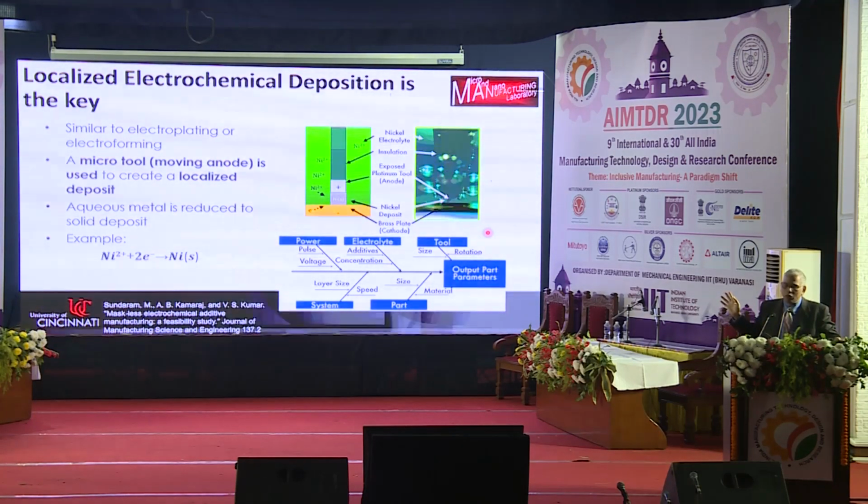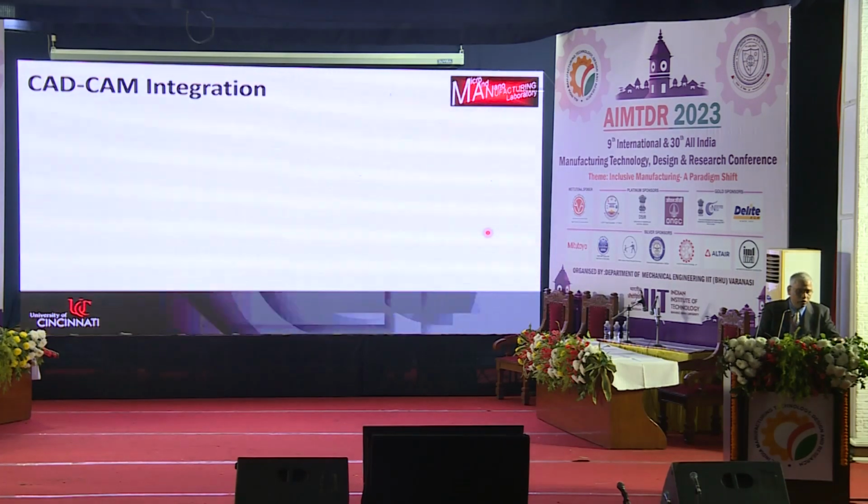I am not listing everything in this fishbone diagram. Only some of those things, which in my opinion are the most dominant influences. For example, electrical parameters are many, but the pulse frequency and the voltage play a very big role compared to the other parameters.